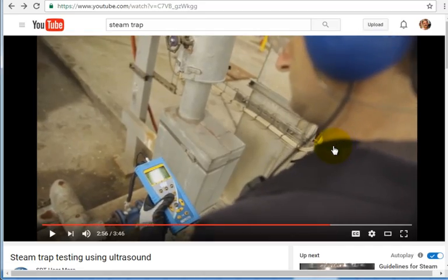So it's interesting that the one that fails closed produces the possibility of water hammer in your piping system, because the condensate's not getting out. You get more condensate flowing in pipes. The steam flowing over it creates a wave. Once it builds up a wave, it captures it and pushes it, and now you've got a slug of high-density material waiting for a turn. And when it turns, it hits an elbow or something, boom.